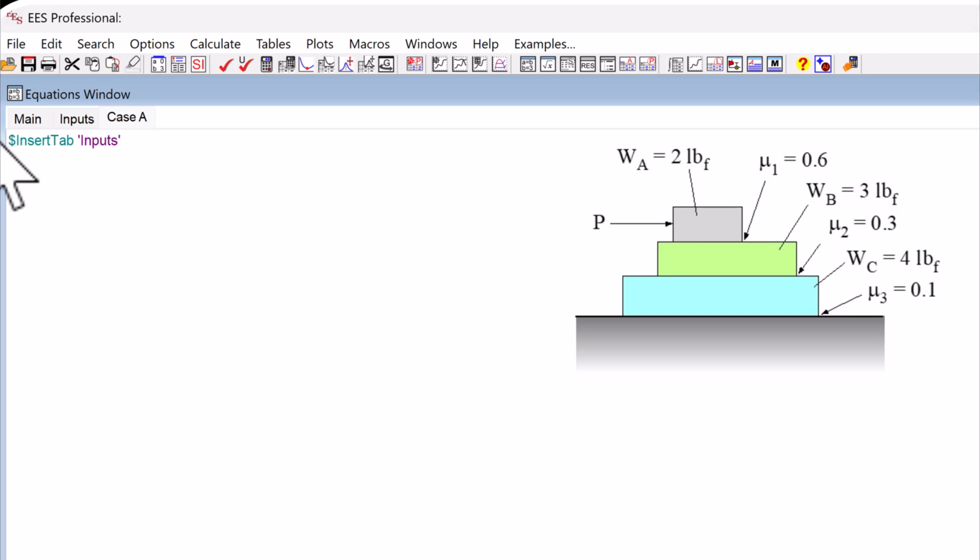So the solution is that I guess this is book A slides, and it's going to be N. So this is my normal force. If only book A slides, then my normal force is only the weight of A, and then my friction force at the point where the sliding is just impending would be mu1 times N, and the sum of forces in the x direction equals 0.